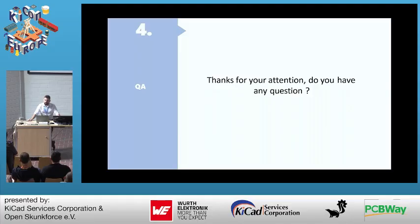So first question, if we do via in pads, yes, we can do via in pads for sure. I did not mention it here, but it's totally possible. Most of the time we will recommend to fill it with resin, because we want to avoid that the solder paste goes inside the vias and possibly creates some issues, some shortcuts maybe in the PCB. So yeah, it's totally possible. On our website, you can select it. I will show you on my laptop after the talk where you can select it.